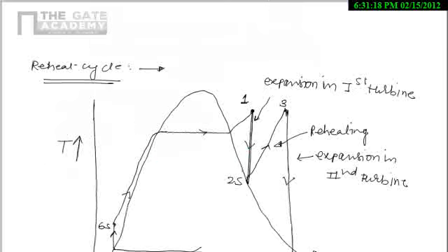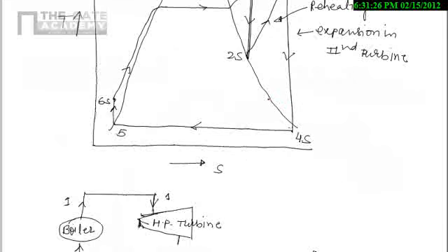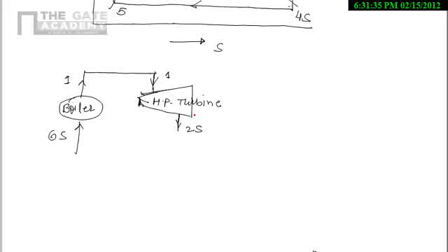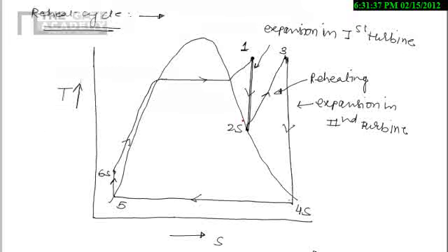because here if you see why I am calling it high pressure, if you see the pressure line, one is this, the second one will pass through this, and for the other turbine, that is 3 to 4s, pressure is low, that is the low pressure turbine. So that is the difference between high pressure and low. The steam will leave at point 2s here in the diagram.